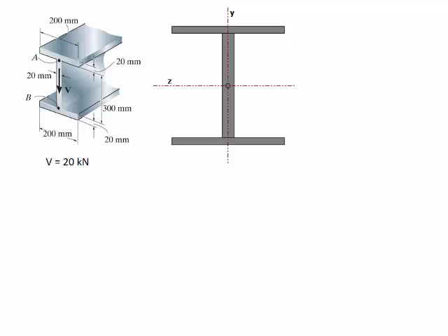In this problem, we have a wide flange beam that is subjected to a shear force of 20 kilonewtons, as shown in the figure with all the dimensions. And we need to determine the maximum shear stress at that cross-section. Note that the maximum shear stress will happen at the neutral axis.